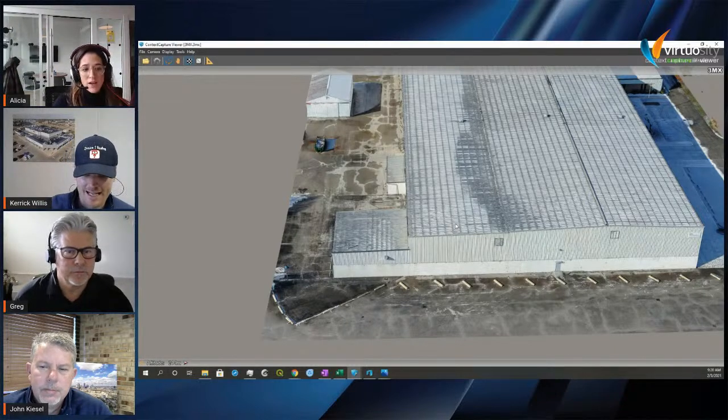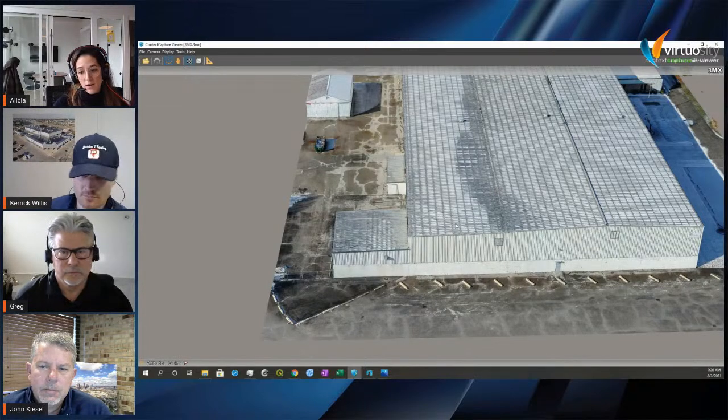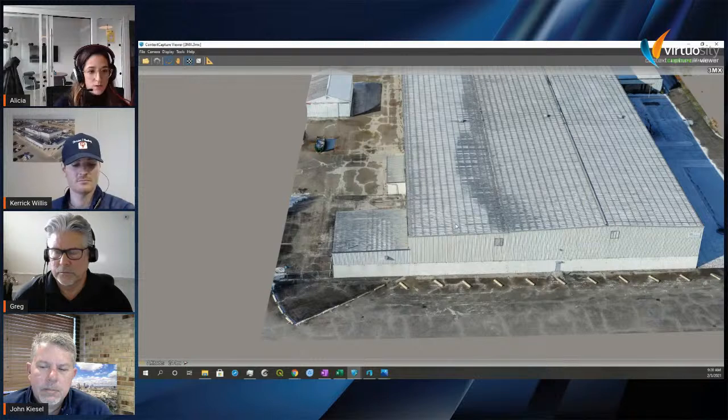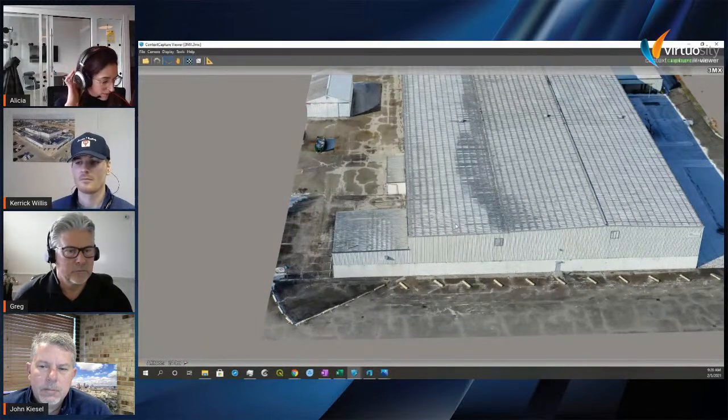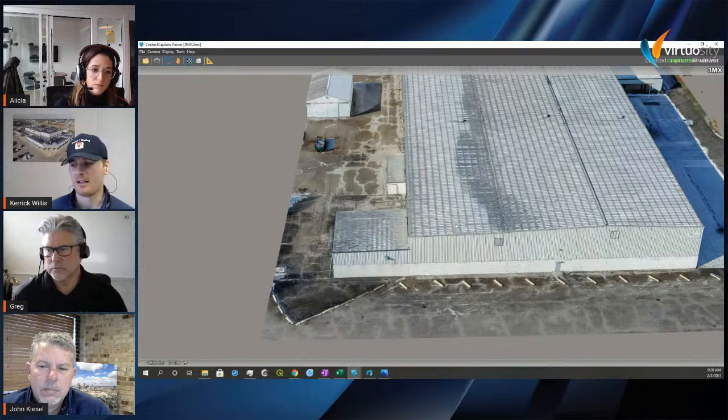Yeah, exactly. Kerry, can I ask, coming from James again, do you use ground control points or RTK equipped drones for a greater precision, or what do you use for your final accuracy? So I normally will run scale constraints for measurement accuracy, so that way I ensure I have good measurements. I don't go for geolocated or high relative accuracy on my maps. I go for a relative accuracy, not an absolute accuracy.